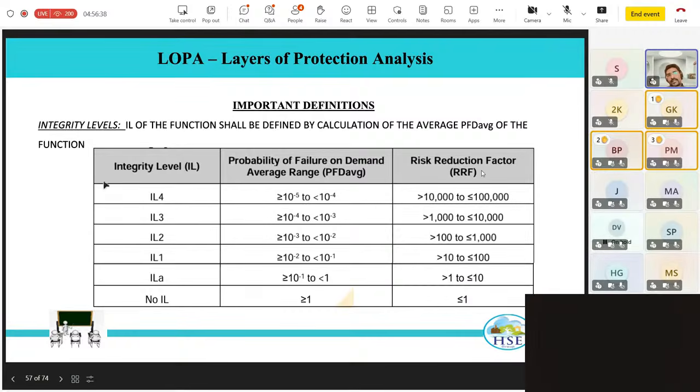Whereas when we have SIL 3 in our oil and gas, fertilizers, pharma, downstream refineries and everything, there is a directive not to go for SIL 4. Instead, relook at the possibility of reducing the SIL or reaching ALARP through additional safeguards, or they insist on relooking at the design aspects of it.